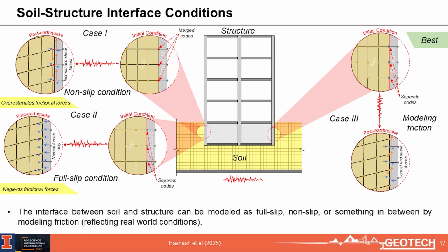Now, in dealing with soil structure interaction, it turns out an interesting problem we often have to deal with is contact, the interface between the structure and the soil. And not all contacts that are implemented in finite element codes are good. They have to be dealt with carefully and with prudence. And the formulations have to be thought out very well. And whether you have a contact that allows slippage or full contact, it depends on the ground conditions and on the structure you're dealing with. But you need to pay specific attention to that interface contact because it impacts the forces that